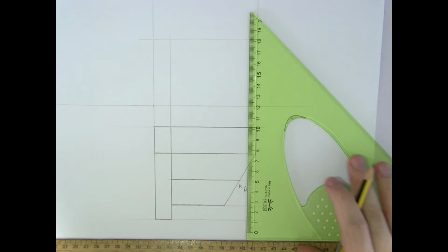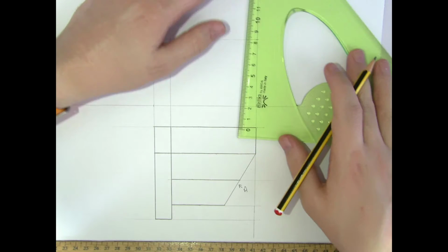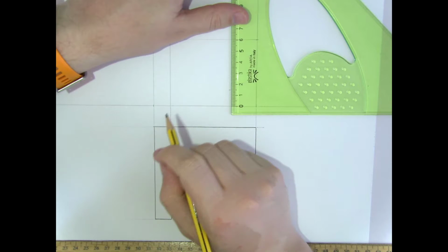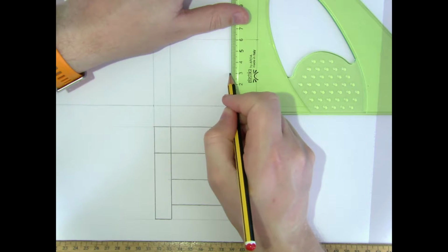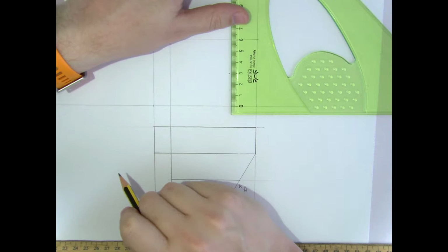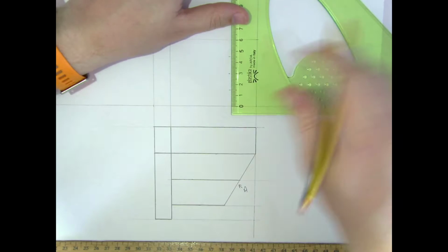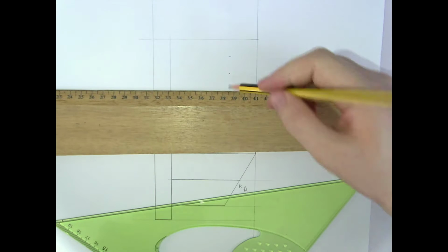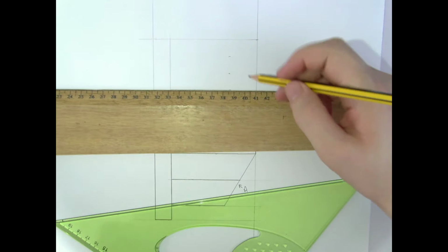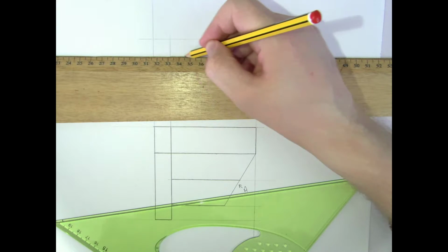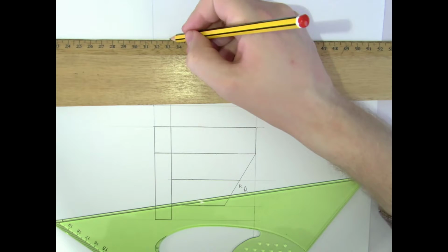And then we'll mark up the height of each step. So the first step is up 15, given in the question. The second step is up another 15. And then we're told that the height of the back step is 45 millimeters. So I can mark that in also. So draw them in lightly first, as they are going to be cut by the sloping edge that we have. And we can darken those bits in afterwards.